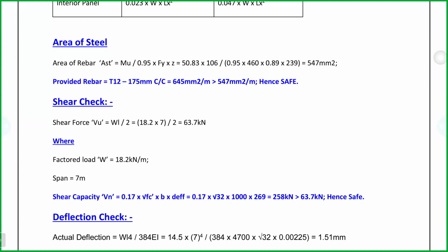For example, for a beam, we will directly go for the beam dimension. But only for slabs and walls, we take it as per meter width. So we'll design per meter width, and whatever reinforcement results, we will lay down for the entire slab, whether it is 20, 30, 40, doesn't matter. You get my point?